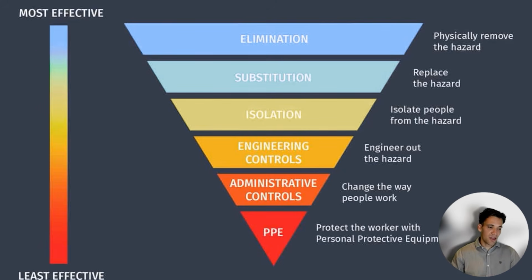Well, now I'm going to explain a concept called the engineering hierarchy of controls. We're going to clearly define what we mean by an appropriate control. What is a sufficient level of control? So we're going to talk about all of the different controls that we can have in place, going from eliminating a hazard, substituting, isolating, to administrative controls, to simply PPE. We're going to talk about them in terms of their effectiveness, and then what is a sufficient control to have in place.